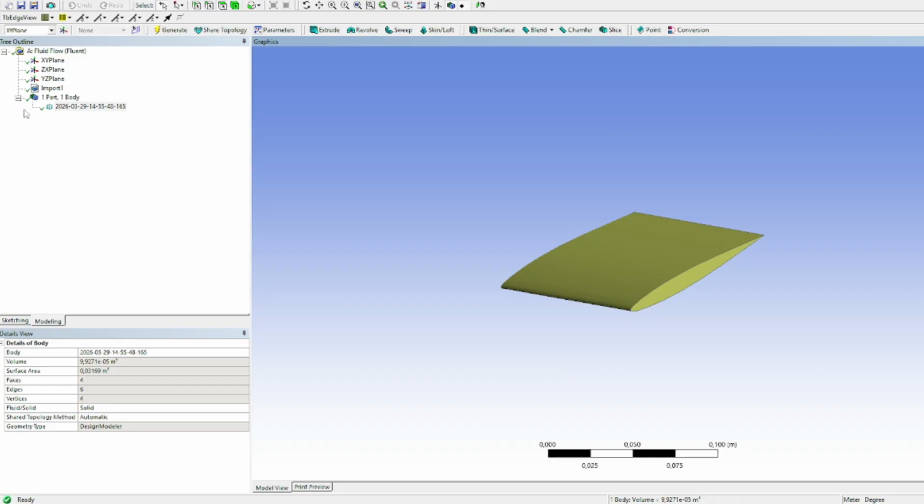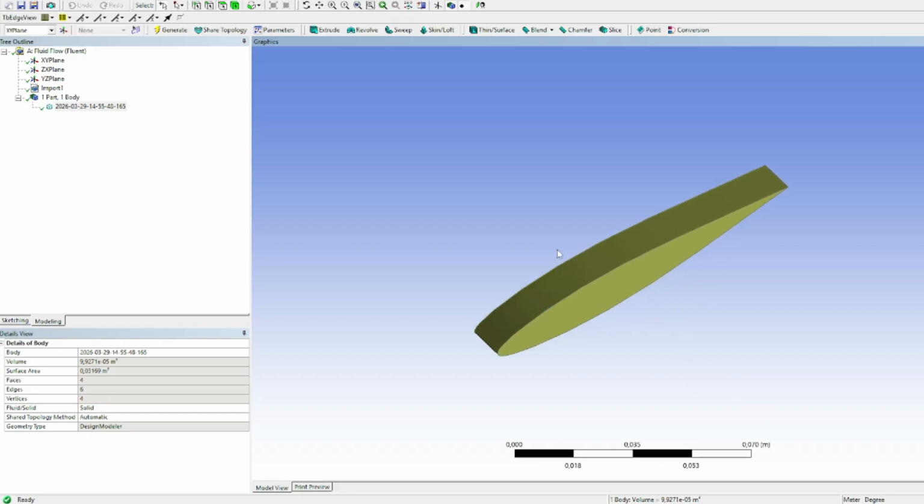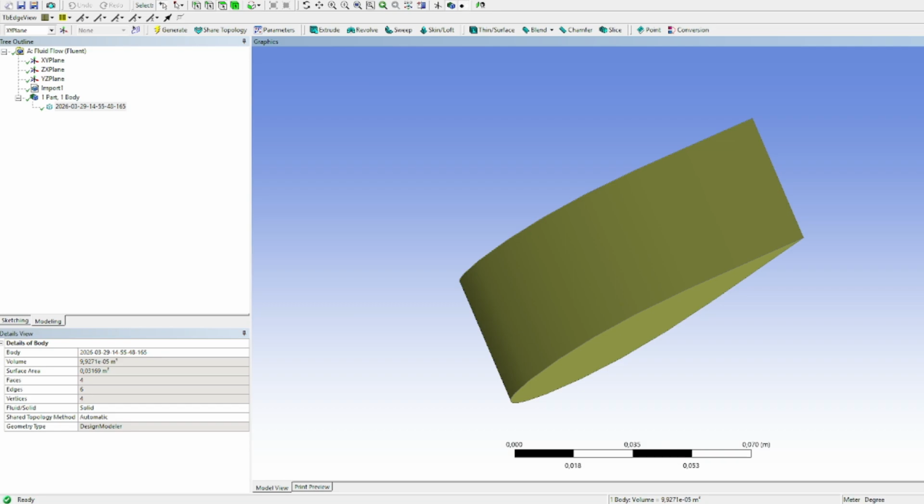Okay, now once you have it, make sure that on the solid appears this icon, like a cube icon. If it appears as just a face, an icon of a face of a cube, it's just a surface. So Ansys will erase it because it's not a model, and you will have to make it a solid, that face, or stitch it on Fusion. So we can close here.